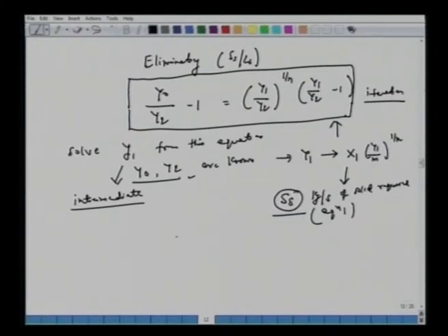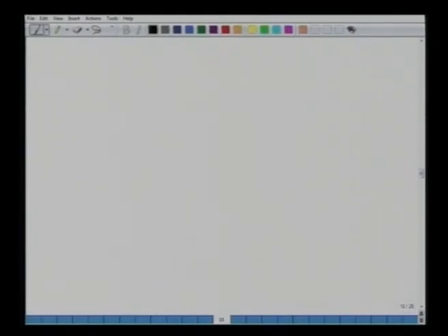From x1 we can go back to equation 1, and from there we get the solvent amount. Now let's mark all these points for the two-stage contactor. Say we have y0 and x1. Go back to the previous schematic for the two-stage contactor: we have y1, x2, and then y2 and x3. So let's mark these points on the graph. Or we can solve graphically as well. We start from here, with this y versus x, and let's say this is the equilibrium diagram.